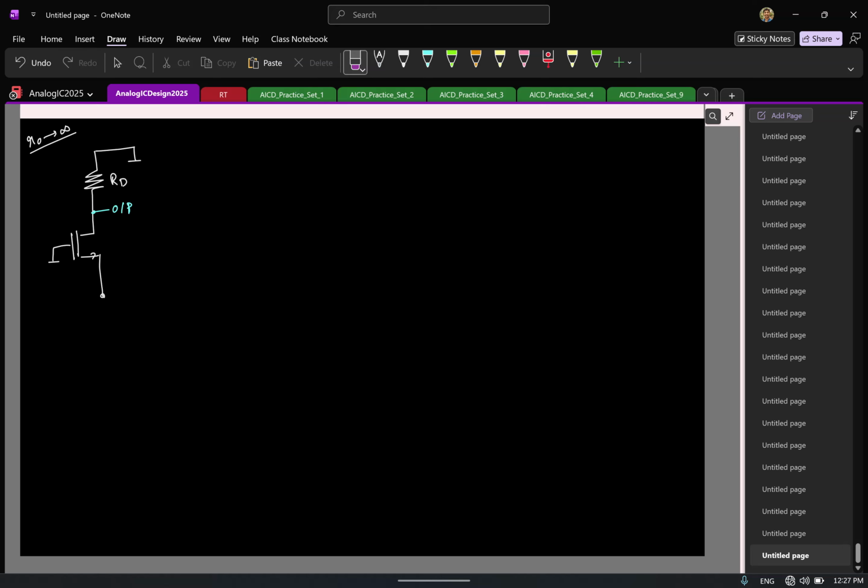So which means in practice, you don't know what is the source resistance RS, so you'll have something like this. V_in and RS. And again, since I'm interested only in the noise calculation, I'll make V_in to be 0. So here, what is the input impedance? r_o is infinity. So what is the input impedance? 1/Gm. So input resistance is not infinity. So here you will have to find both voltage and current. So let's do that.